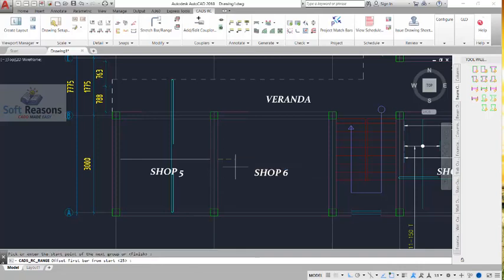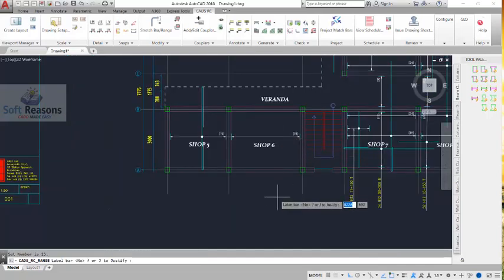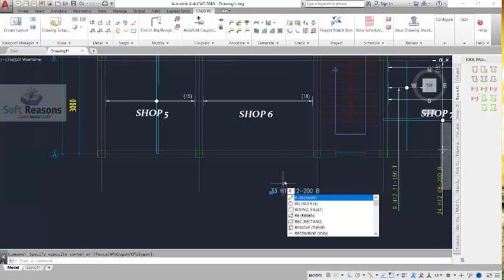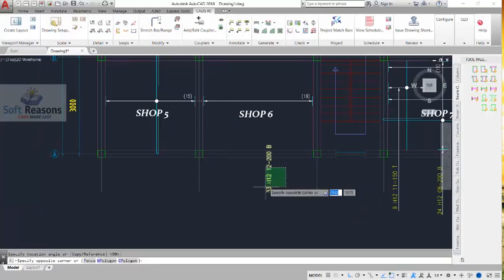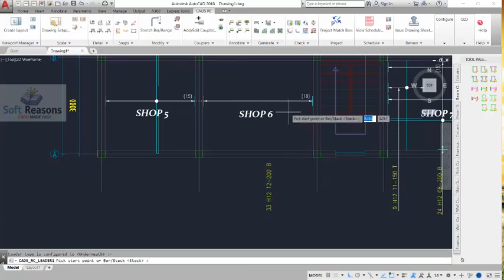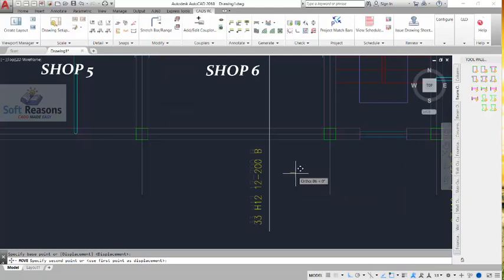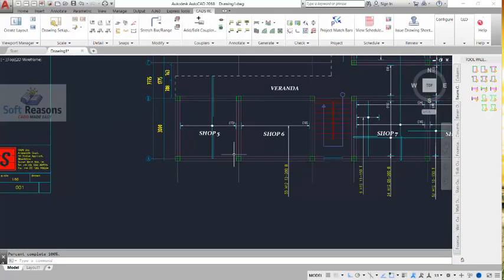Okay, so you enter again. At the point of finishing, you have to start from here because this panel, shop 6, is going to be included. So you enter again for the first 25, for the end 25 you also enter right there, enter again, and then you have to finish it. So we have this. After which we proceed, we place it here, rotate it this way, and then move it to this point. Use the leader line, pick this, take it up to this point, escape right here, and move it with M on the keyboard, closely. So that is it in these directions.